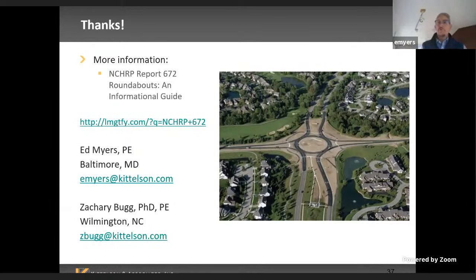We can't always do that, and so it can get a little bit more complicated, depending on what kind of plane you have going across the intersection. But ideally, everything drains away from the central island. That helps in colder climates like Canada to get everything drained away so that there's no icing or snow accumulation.